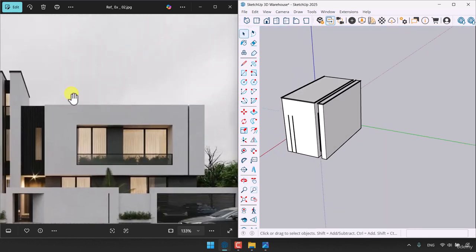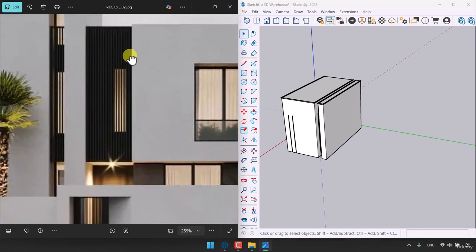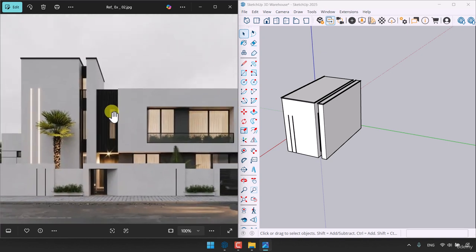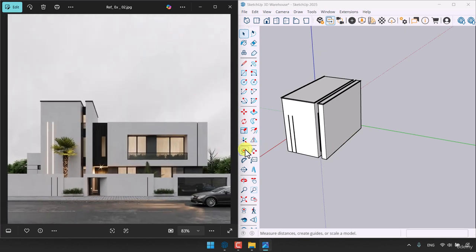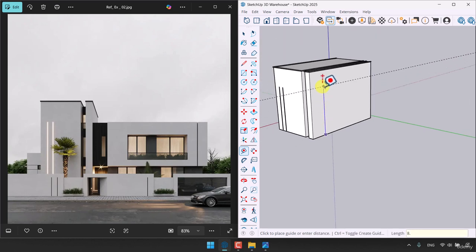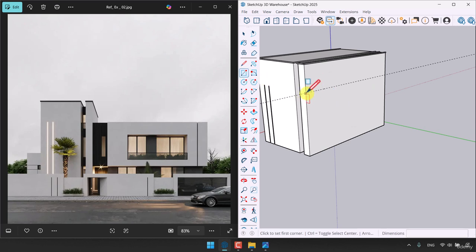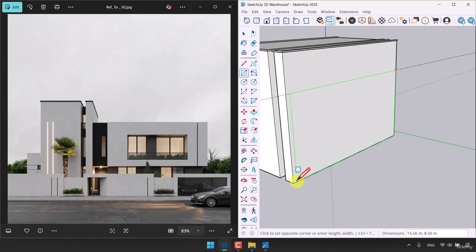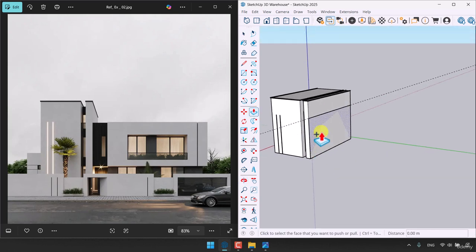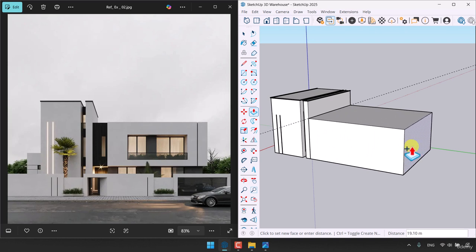Next step is this part of my project, which is the separated rectangle. So for this reason, I need to focus more on this image. Actually, they are on one face. There is no type of backward or forward design. So I'm going to use the tape measure in here, tape it about 8.5, and I'm going to click on the rectangle another time, draw my rectangle like this, click on the push or pull option, and start pushing it like that, about some number.